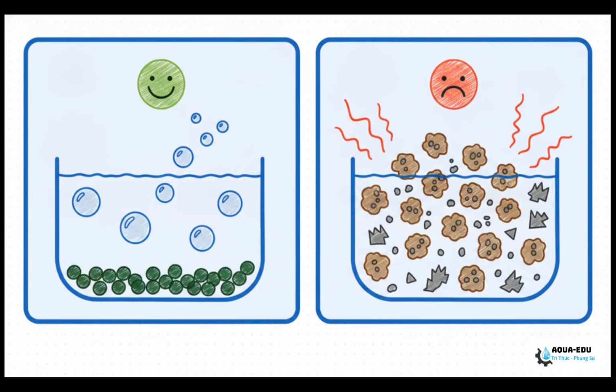Over on the healthy side, a stable UASB gives you high methane production, a nice stable pH, and granular sludge that settles perfectly. But look at the failing UASB. It's trapped in passive acidification. Your VFA to alkalinity ratio spikes way over 0.5. And those precious granules end up trapping tiny CO2 bubbles. They completely lose their ability to settle, and they literally just wash right out of the tank.